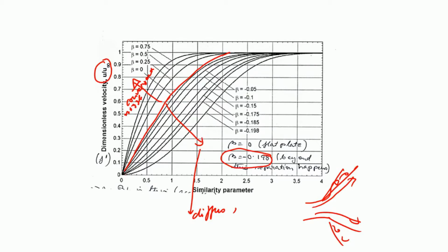As you can see, the boundary layer profile slope is almost equal to 0, because the shear stress is nothing but the slope at this particular point. So, the boundary layer is sagging and it is actually equal to 0 at the wall. That means the wall shear stress should be equal to 0 at this particular point.